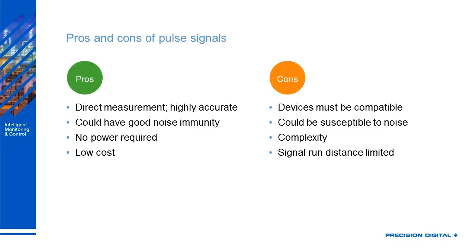And as I spoke earlier, the signal run distance is limited. It's not that there's particularly any problem with running a signal over a long distance from a voltage perspective. The resistance of wire is very low, and it's going to propagate perfectly fine as far as speed goes. The real problem with running your signals long distance is going to come down to noise.